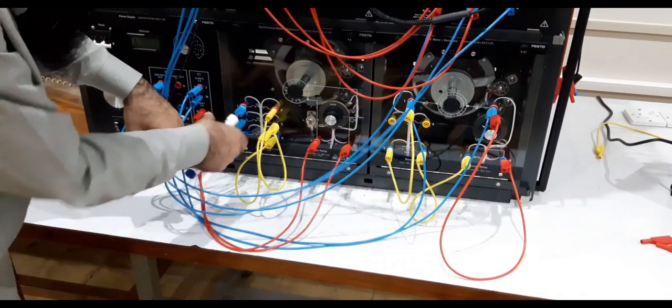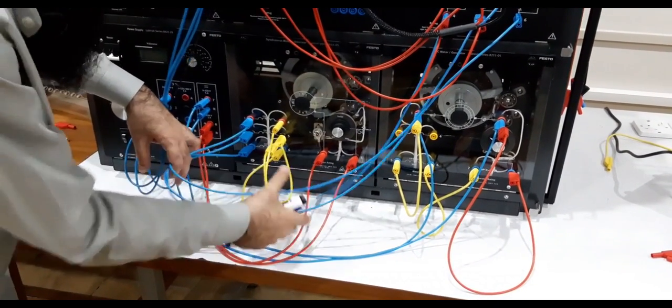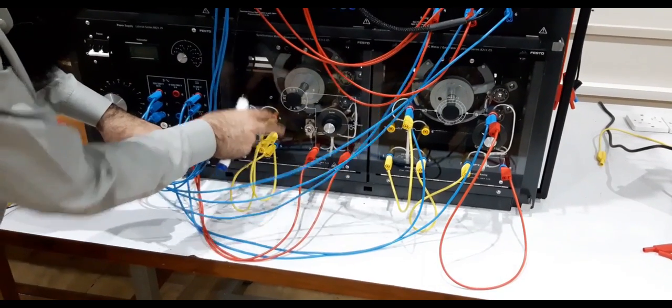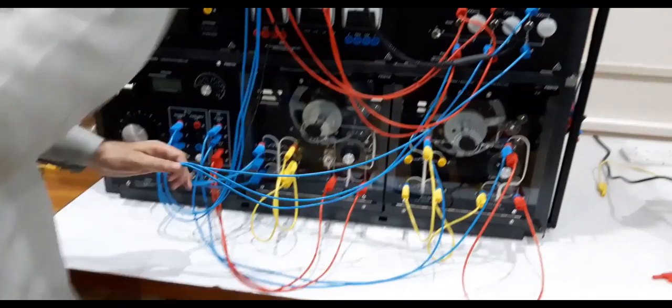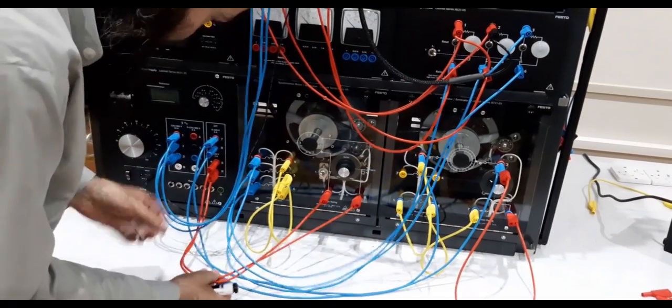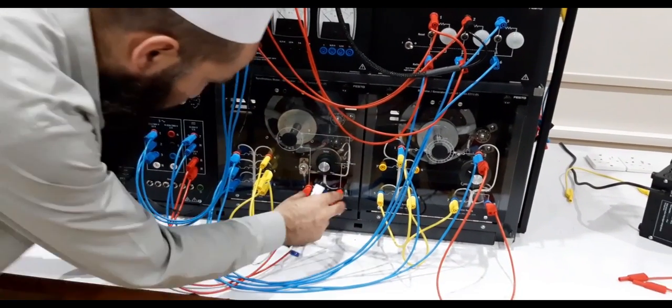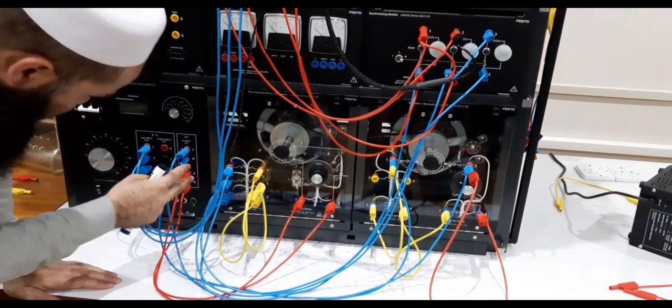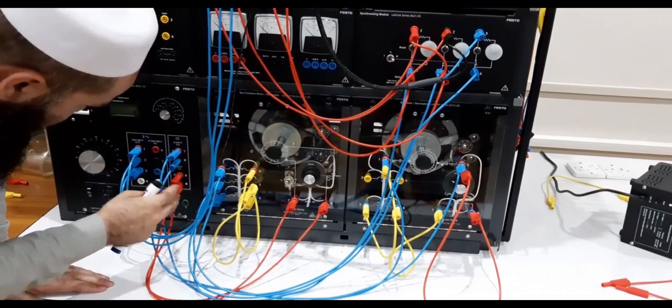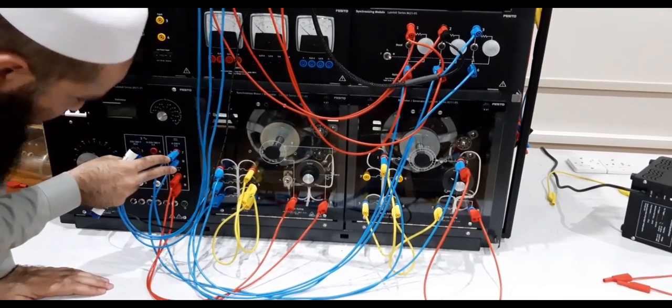So this is basically a Y connection. This is the armature of the synchronous machine. This is the field of the synchronous machine. And as I have discussed on the board, this is the DC supply. So here this DC supply is connected to the rotor, and this is a fixed supply. We have here two possible ways of supplying the voltage. One is fixed supply, one is variable supply.